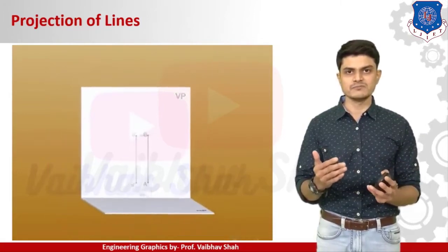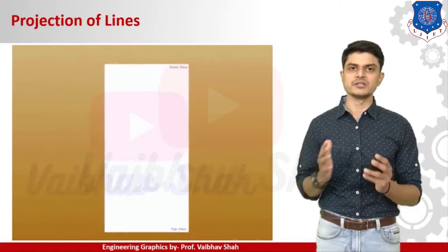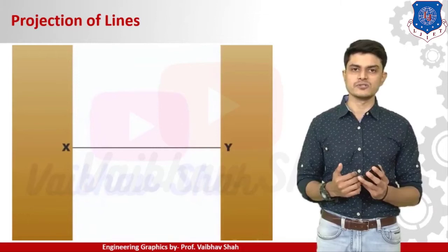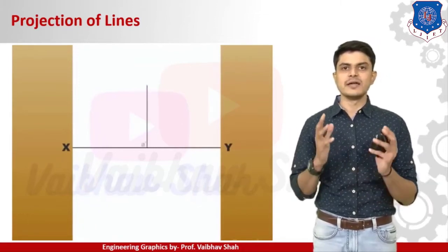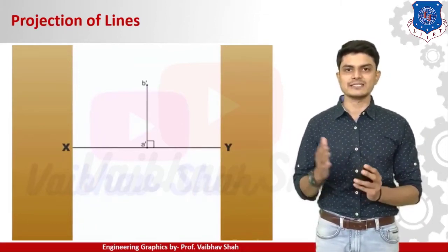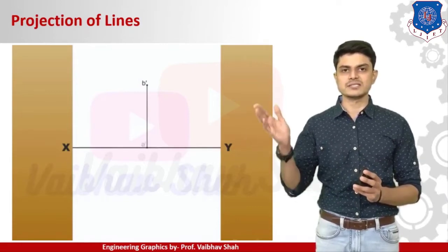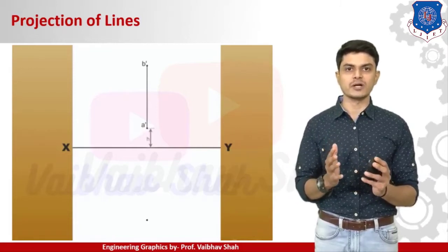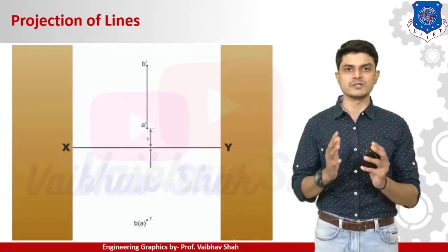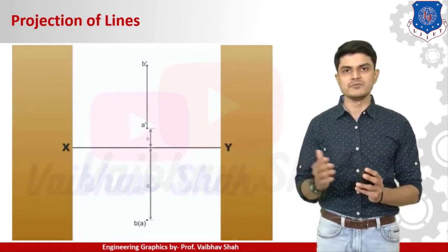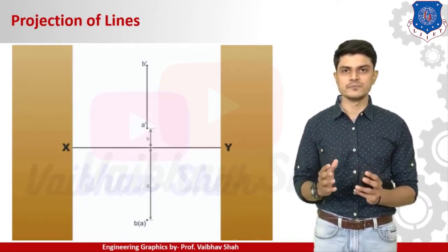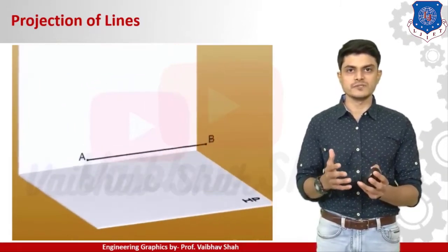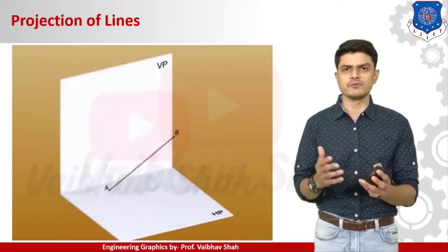Now in the next step, we'll try to convert this 3D representation into 2D representation. So let us revolve this plane across the horizontal dimension, and let us give the intersection line as xy. Let us plot the first line, which is a certain distance away from your HP or your xy. So we have plotted this line, which is nothing but our front view of the line which the observer had witnessed in the previous section of the video. Now we will be plotting its top view. We have observed the point view, so now we will be drawing a point view in the top view.